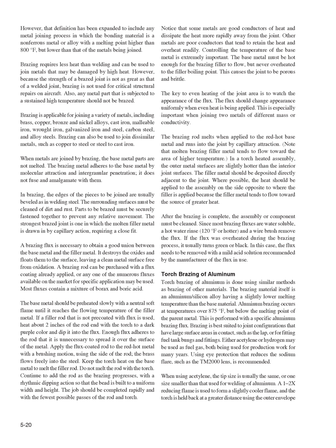The key to even heating of the joint area is to watch the appearance of the flux. The flux should change appearance uniformly when even heat is being applied. This is especially important when joining two metals of different mass or conductivity. The brazing rod melts when applied to the red-hot base metal and runs into the joint by capillary attraction. Note that molten brazing filler metal tends to flow toward the area of higher temperature.